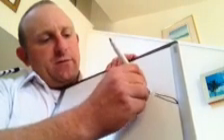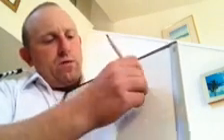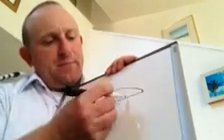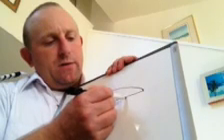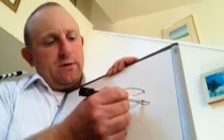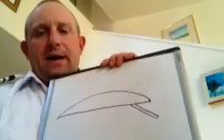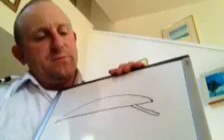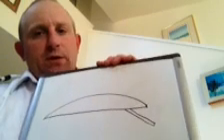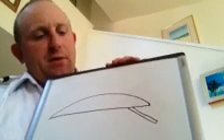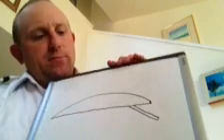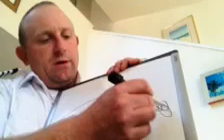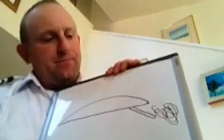From there, we have some aircraft that have been equipped with what's called a split flap, and that's where the flap tends to drop like that from under the surface of the wing. And with a split flap, we do get a little bit more lift than we would get from a plain flap. However, we get much more induced drag because of the turbulent airflow that's created behind the flap.